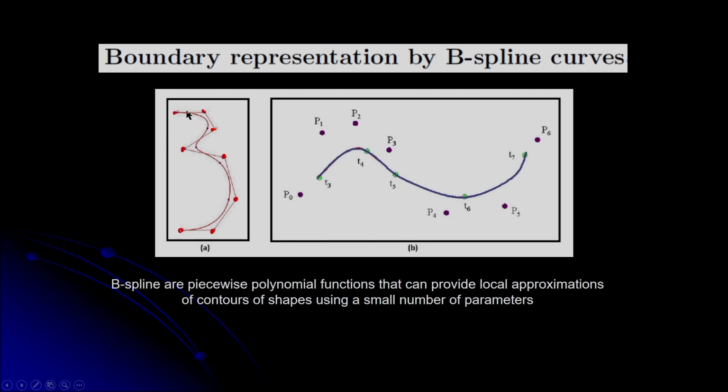These control points divide the B-spline curve into a number of curve segments, and this subdivision of the curve can also be modified, and B-spline curves having higher degrees of freedom can also be considered for curve design.